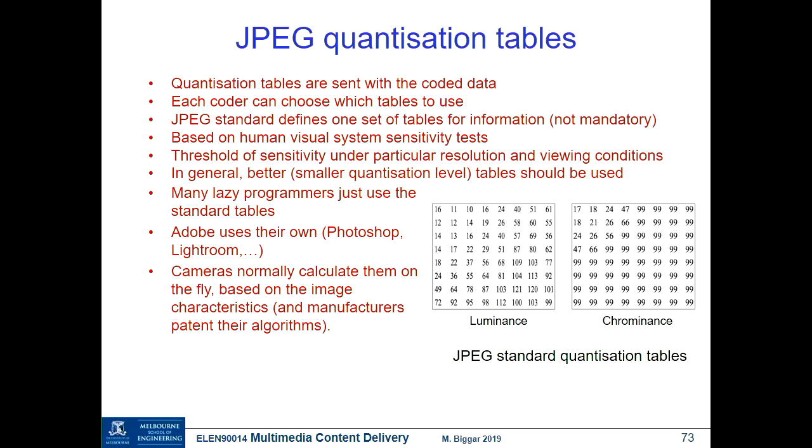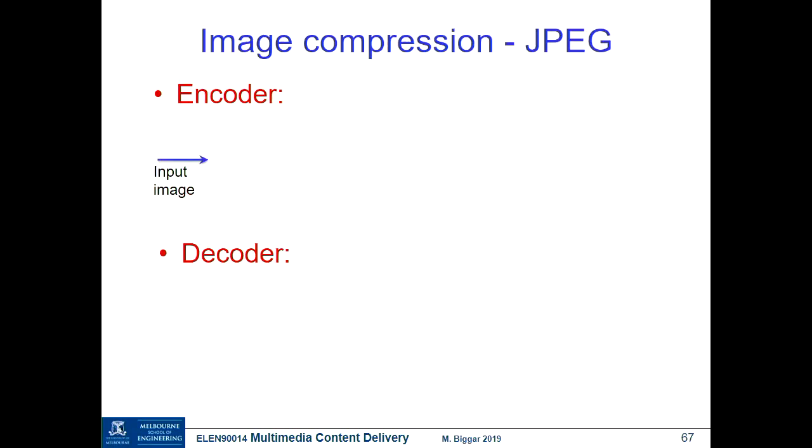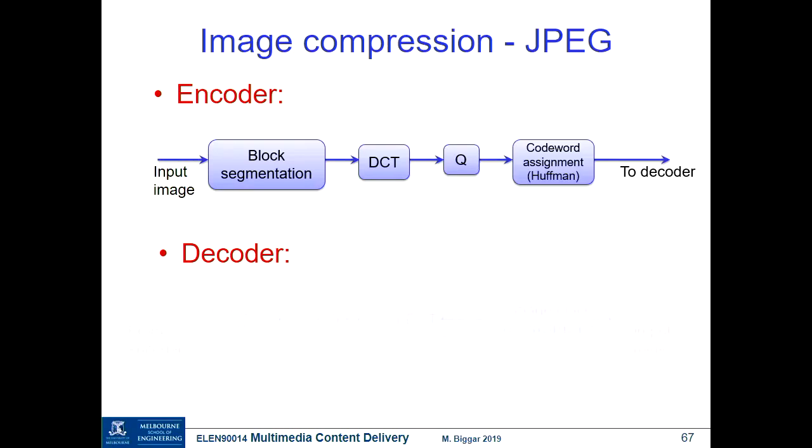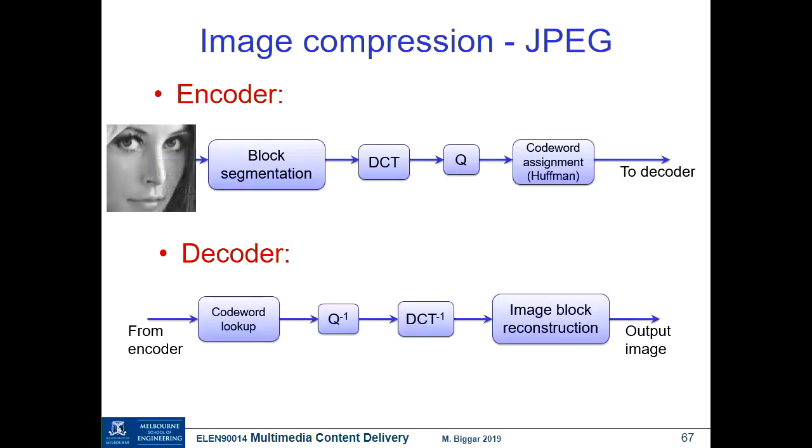So that's the essence of the JPEG coder. It involves these blocks that we would expect from our earlier discussion, with a few subtleties about reading out two-dimensional arrays, quantizing according to the particular frequency characteristics, and that differential coding for the DC coefficient.